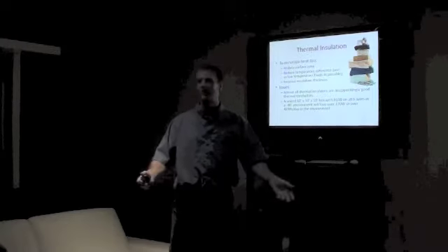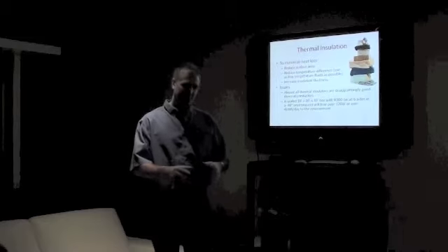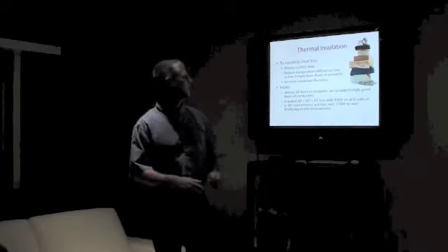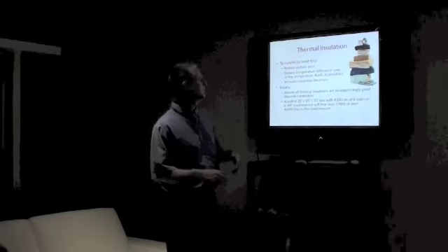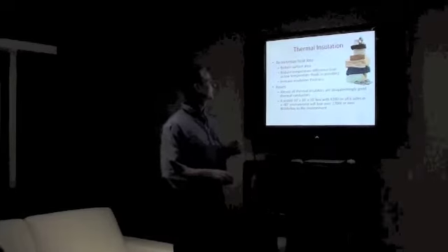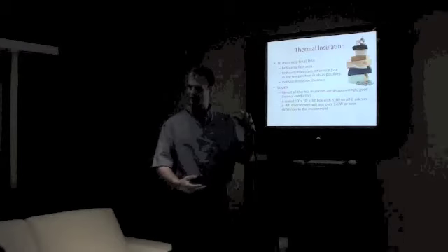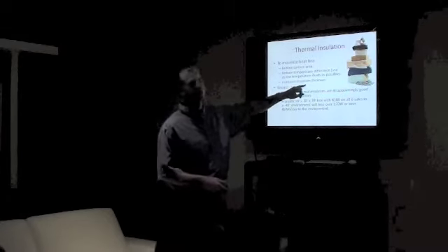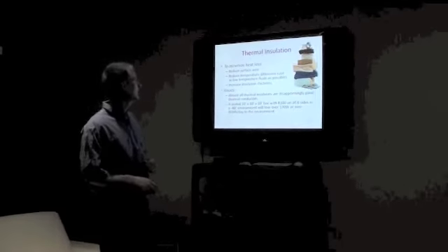So if I had some large process with a lot of heat involved, if I can transfer heat at lower temperatures, I'm likely to lose less heat to the environment, so it will be easier for me to influence where the heat ends up. And the last one is to increase the insulation thickness. I should have put quality also. If I had a higher quality insulation, it will reduce it.